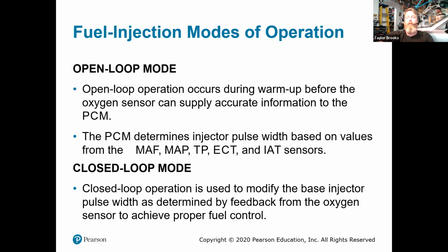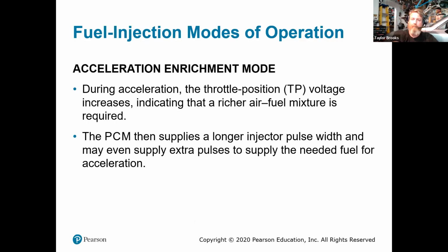But when we're in open loop, we're only in that for a temporary amount of time. Ideally, the engine gets up to operating temperature as quick as possible because we're going to get the proper performance out of the engine, but also the proper fuel economy and reduced emissions.